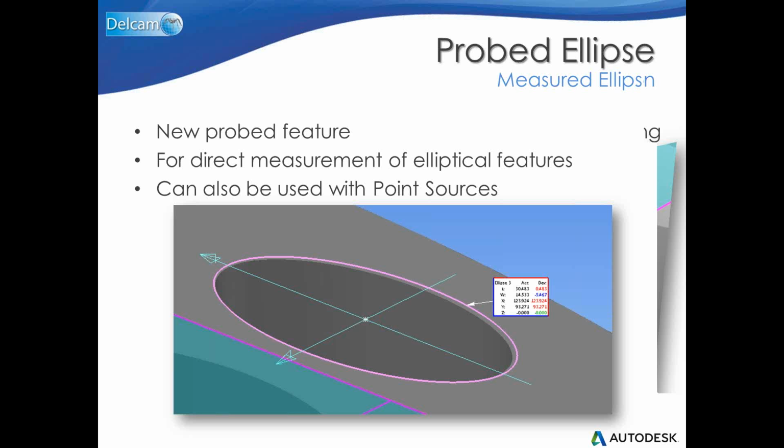Again, about ellipse, we can also define an ellipse as the intersection between 2 items, such as in this case a plane and a cylinder, or a plane and a cone. Another constructed item in this case is a circle, as an intersection between 2 tori, so torus intersection. This is quite helpful when we are dealing with pipework and ducting. I will show you shortly how to create these constructed features.